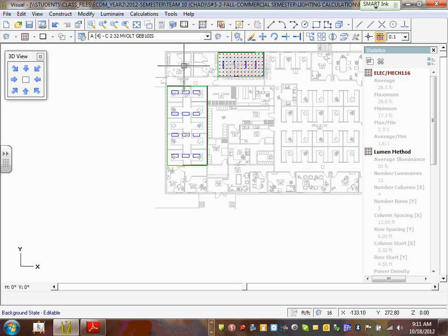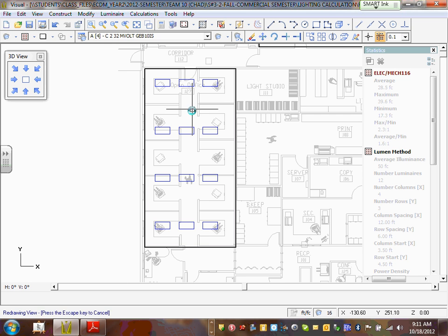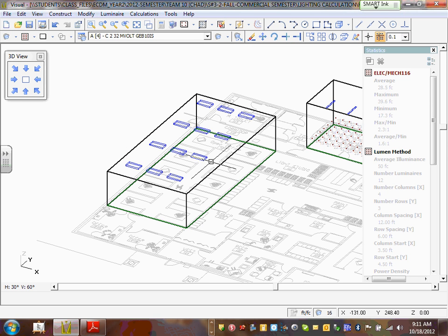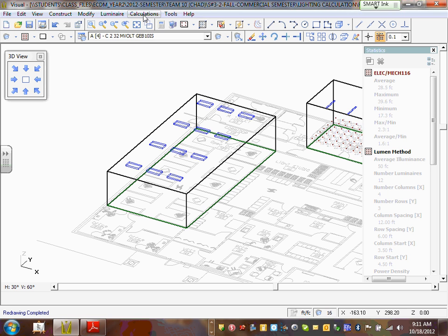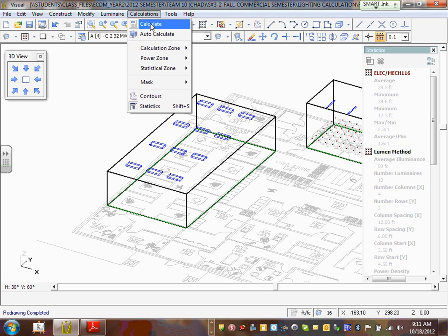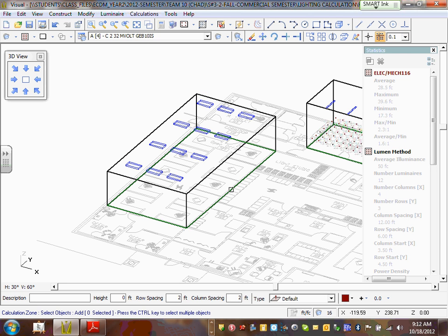Now, before you leave, though, I want you guys to do the following. I need to go do calculation zone, though. Can you guys go look at the 3D, grab a view 3D for it, and go to calculation zone, because I don't have calculation zone here yet. Calculation zone here, and surface, and pick the bottom. Before you click anywhere else, name it.